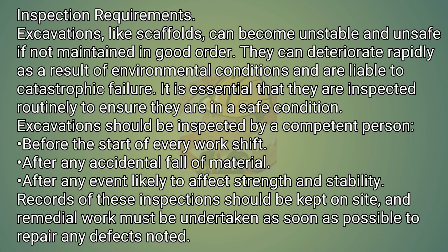Inspection requirements. Excavations, like scaffolds, can become unstable and unsafe if not maintained in good order. They can deteriorate rapidly as a result of environmental conditions and are liable to catastrophic failure. It is essential that they are inspected routinely to ensure they are in a safe condition. Excavations should be inspected by a competent person, before the start of every work shift. After any accidental fall of material. After any event likely to affect strength and stability. Records of these inspections should be kept on site, and remedial work must be undertaken as soon as possible to repair any defects noted.